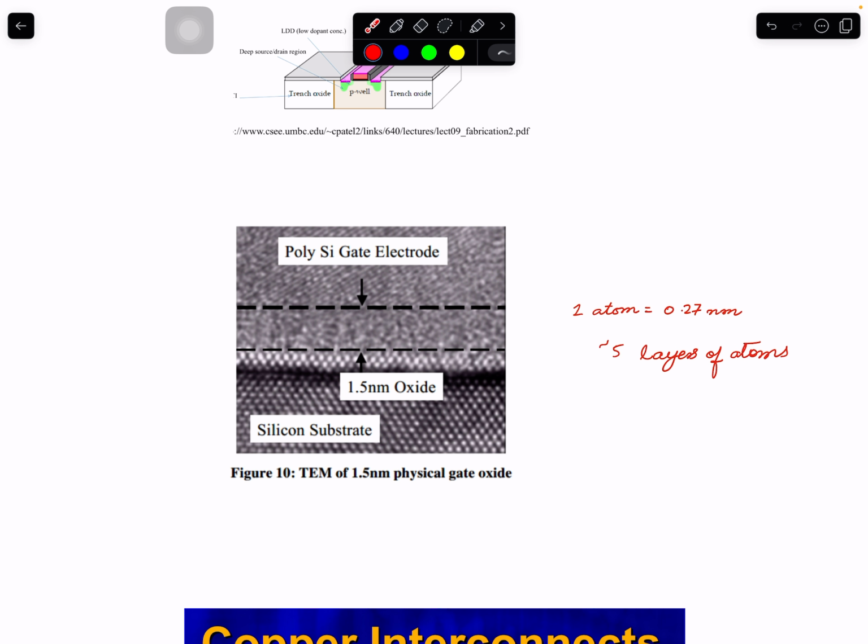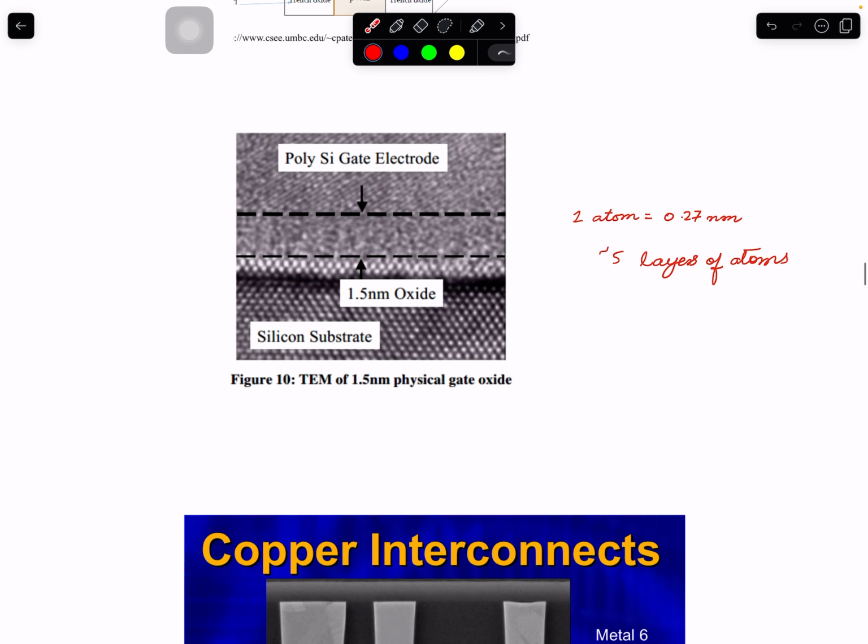And that was the usual way of scaling. You make the transistor length smaller, make this smaller, so that you can reduce this capacitance and you can have a better effect on this surface close to silicon dioxide. But the problem is it's small. I'll talk about those, but your electrons can really penetrate here, kind of have a tunnel effect. Anyway, we'll soon see what kind of problem came as a result of that.